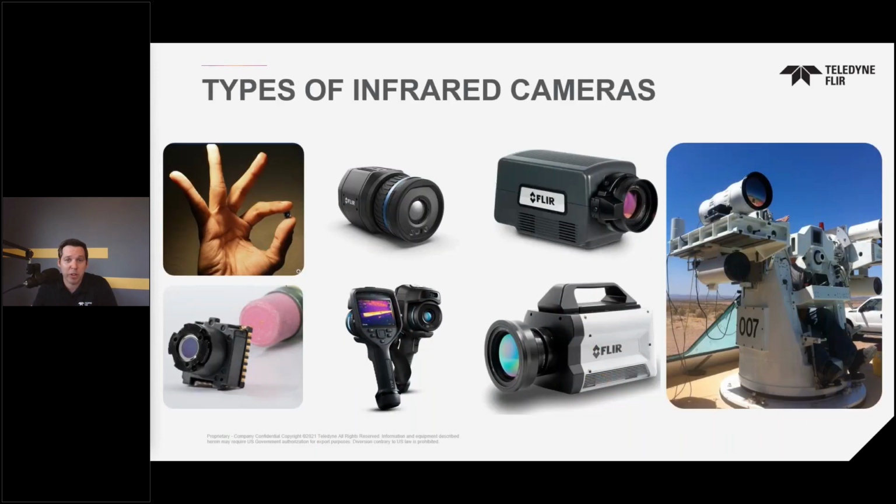For those of you unfamiliar with IR detectors and subsequent cameras, the left side of the chart shows common representation of microbolometer-based systems. These range from very small sensors like the FLIR Lepton in the bottom left to the more common handheld cameras used by many people for quick evaluation of a circuit, motor, or a relatively larger, slower target. On the right side of the screen are examples of cryo-cooled cameras, also called photon counters or quantum detectors. These systems are much higher performance and are typically the models of choice for engineers and scientists due to their flexibility and access to the raw data.